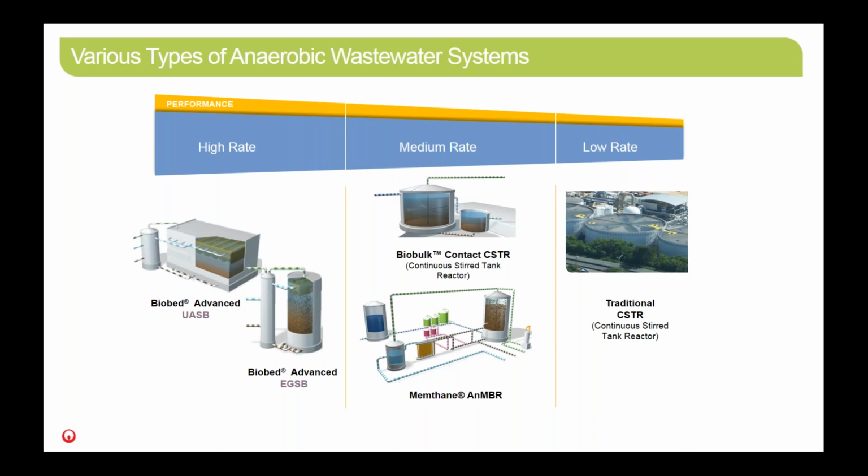The newer technology on the marketplace is the anaerobic MBR technology, which uses membranes as the biological separation. That is a trade name for Veolia. And finally, for extremely high COD and high TSS applications, it's a traditional CSTR, a continuous stirred tank reactor. It's also the type of reactor you see in most municipal solids digestion applications.